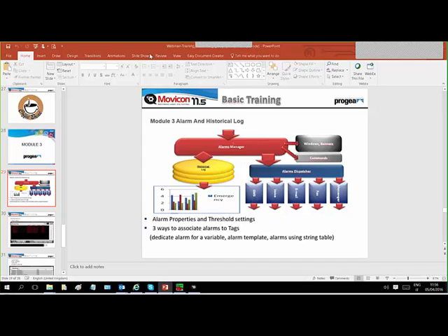There are different ways, and I will show how. Then you can view these alarms through ready objects present in the toolbox, like the alarm window, the alarm banner, and the log window to show the historical logs. When an alarm is on, that is an event. Alarm off, all these events go automatically inside the historical log, so in the database, in a save location. Through this information, we are able to generate reports and perform analysis.